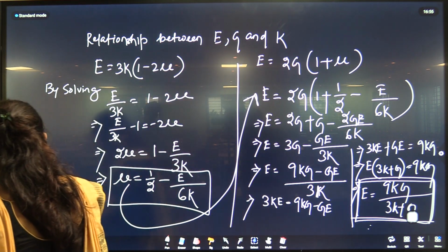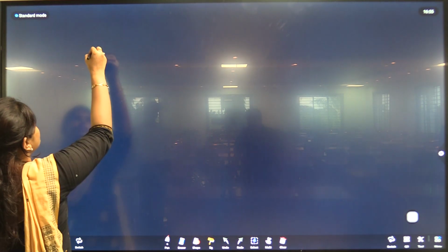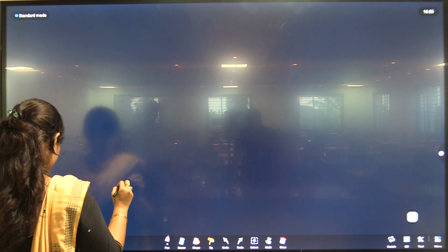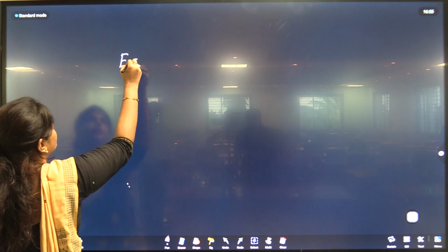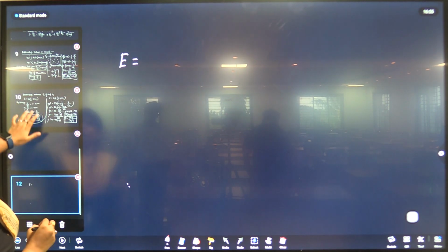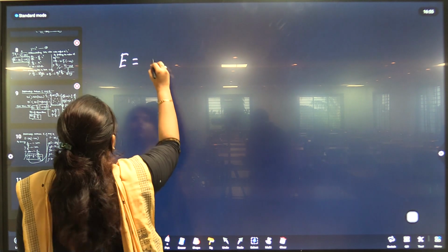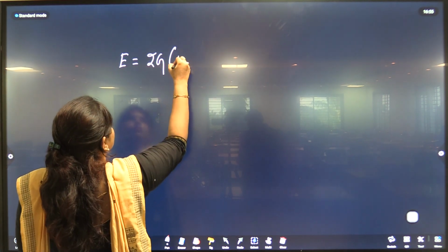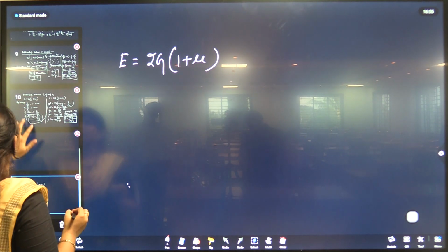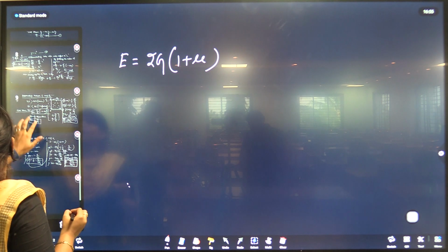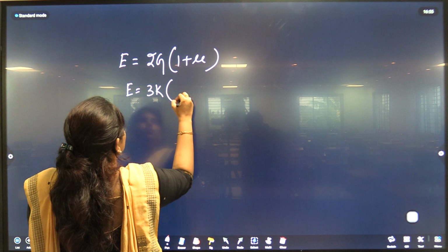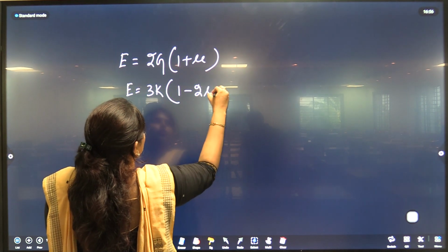So, what relationships we get are: E equals 2G into 1 plus mu. Another one is 3K into 1 minus 2 mu.